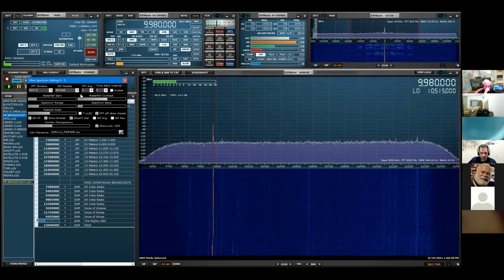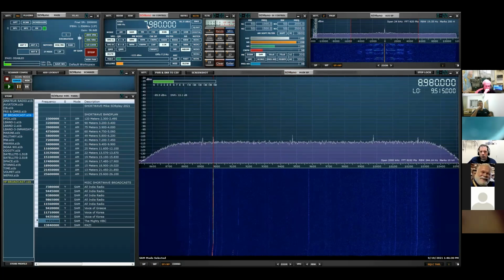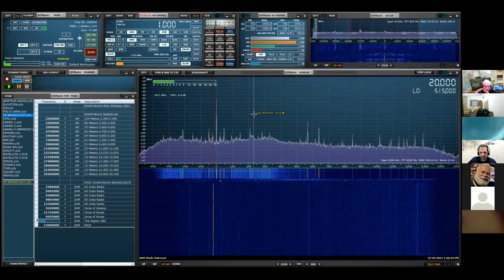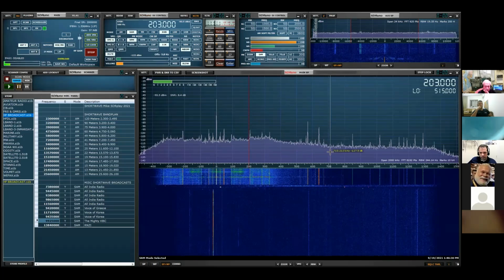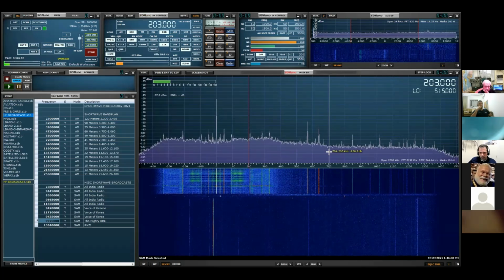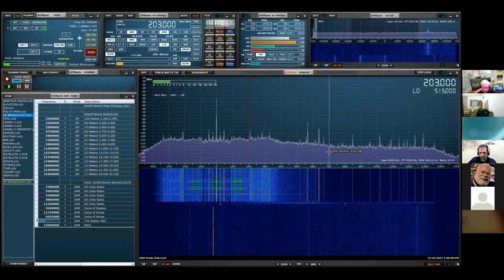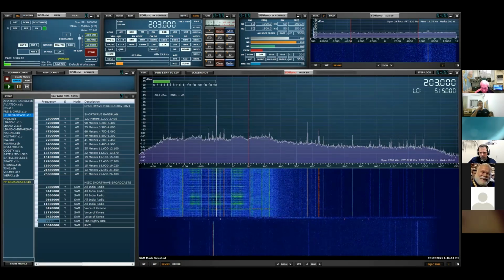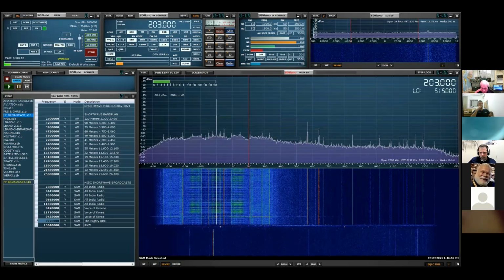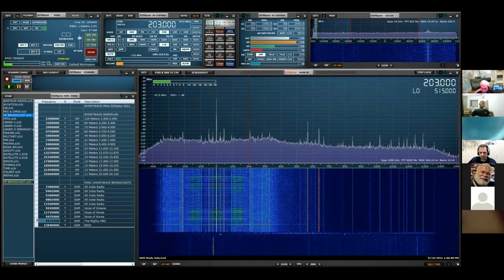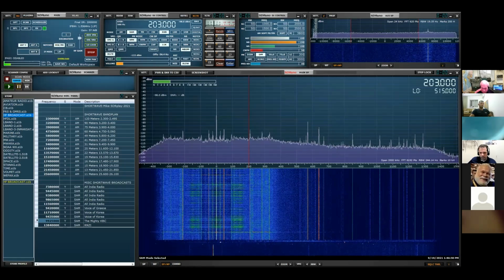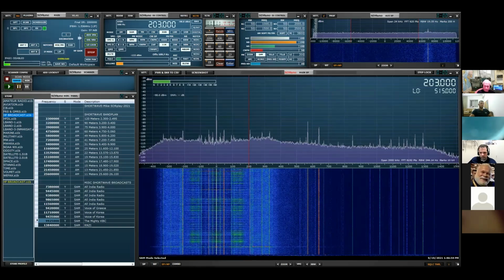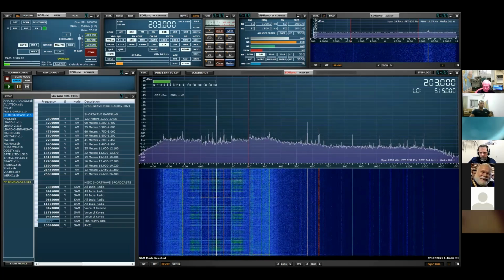I understand. So can you see them if you tune at 15 megahertz? To give you an idea, the kind of display that I'm searching for, if you look at my QRZ page, I have a picture of an ICOM 756 Pro 3 band scope tuned to about 10 megahertz that shows what power line interference looks like on that particular type of receiver.